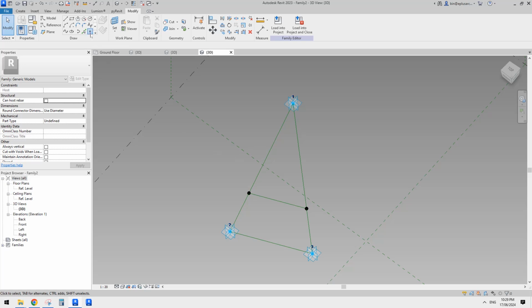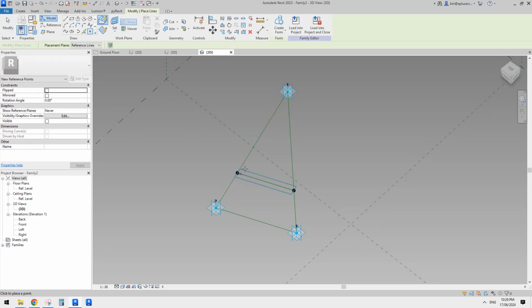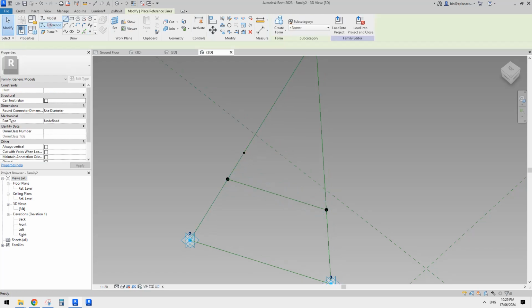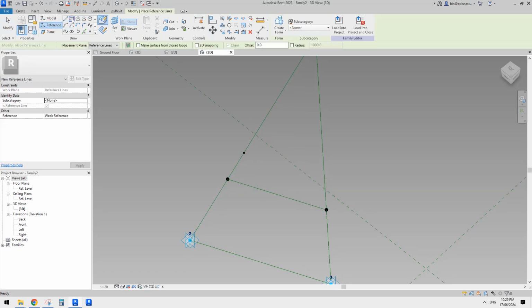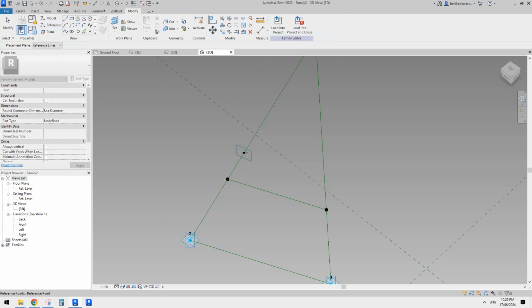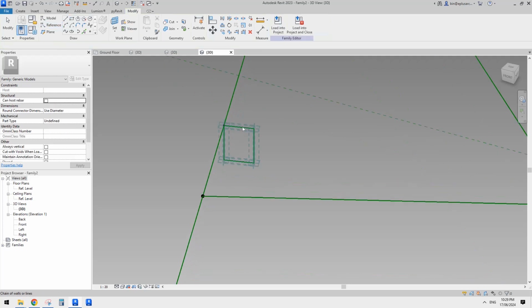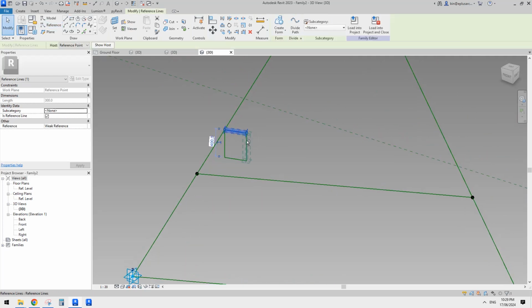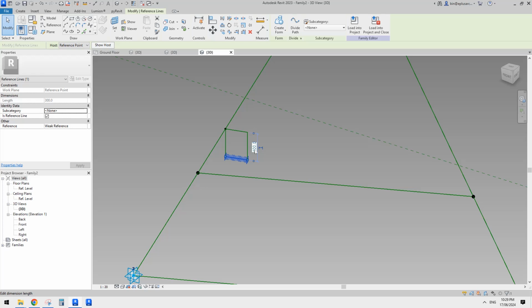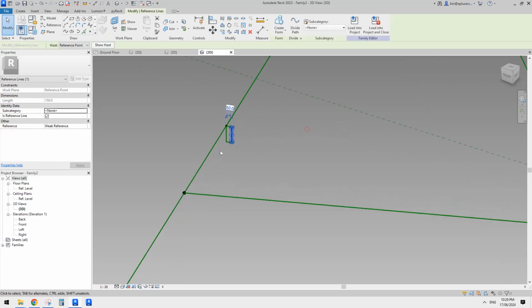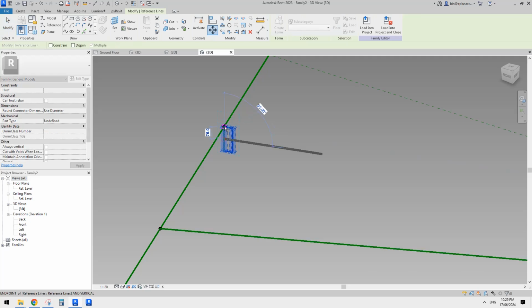So let's place a point, draw on face onto this line, right? And then reference. I'll use rectangle, draw on work plane, set work plane. Pick this, and then I'll draw a rectangular shape. And then let me think about the frame size. Let's make it 150 by maybe 50. Okay, and also let's move it.